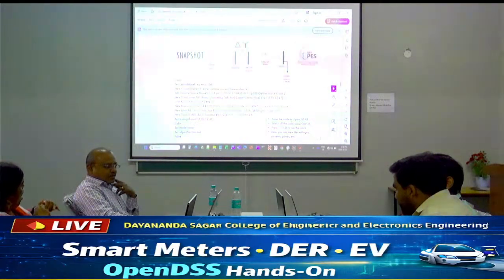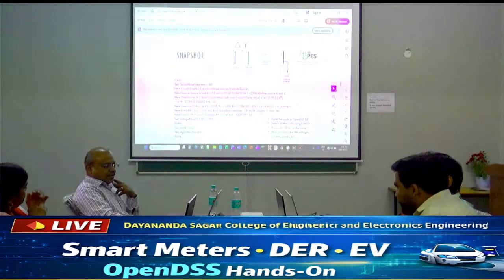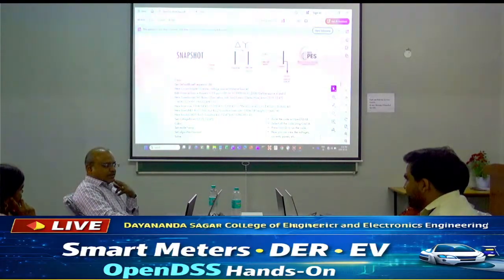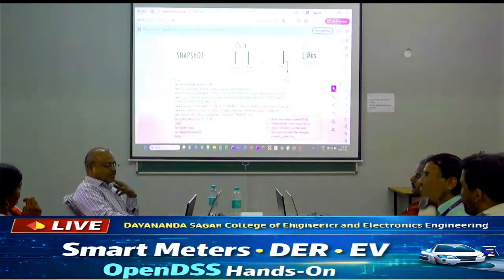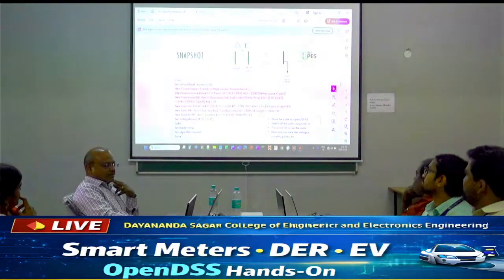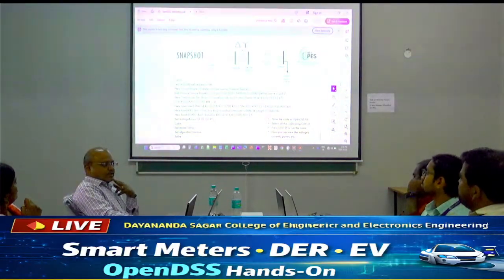And then what are the connections? You have defined the connections, delta on this side and Y on this side. And then the kVs: 115 kV on this side and 12.47 kV on this side. And then the kVA is 20,000 kVA and XHL is 10. So this is how you define the transformer.